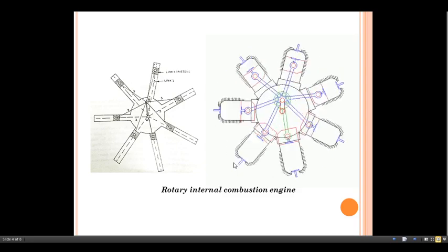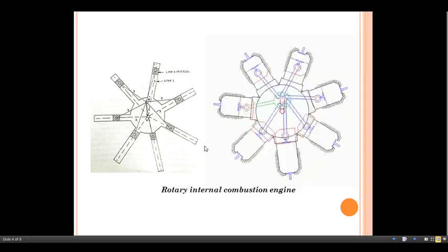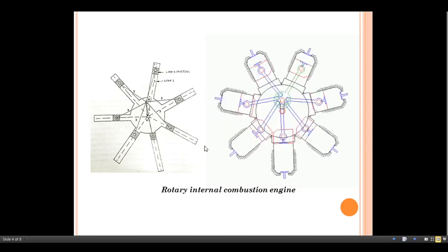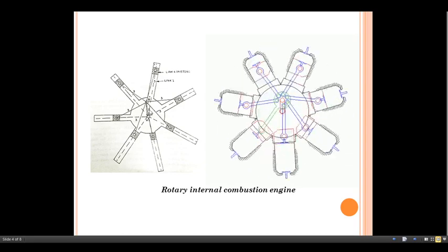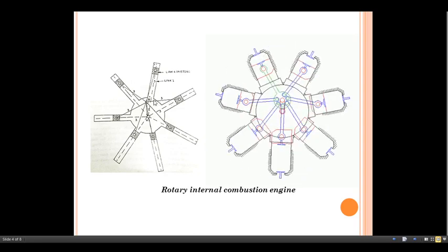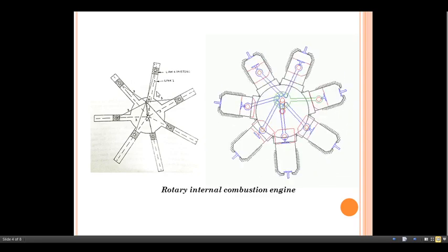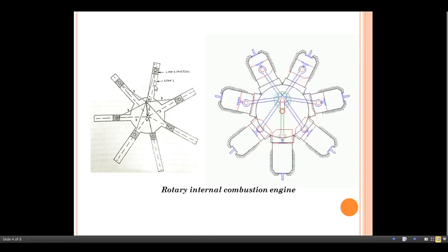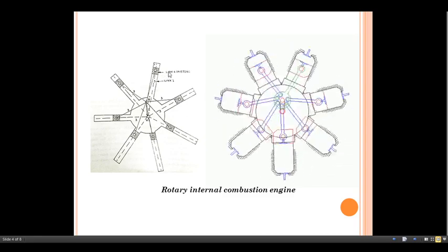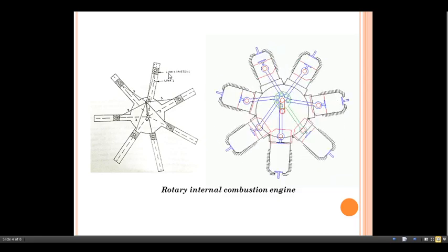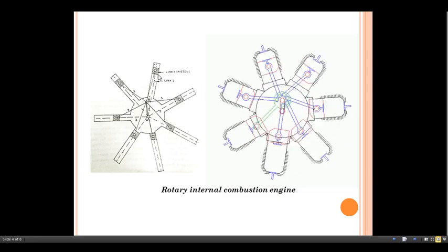This is nothing but again the second inversion of the single slider crank chain. So in this case, if you see here, link number 2 is fixed. Apart from this one, this will act as a connecting rod. The link number 1 will act as the cylinder or a fixed one. And the link number 4 will act as a piston.